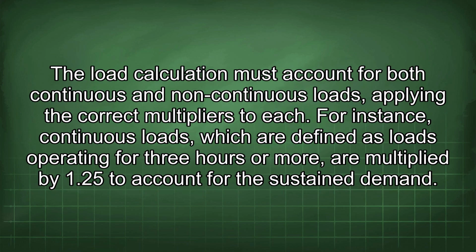The load calculation must account for both continuous and non-continuous loads, applying the correct multipliers to each. For instance, continuous loads, which are defined as loads operating for 3 hours or more, are multiplied by 1.25 to account for the sustained demand.